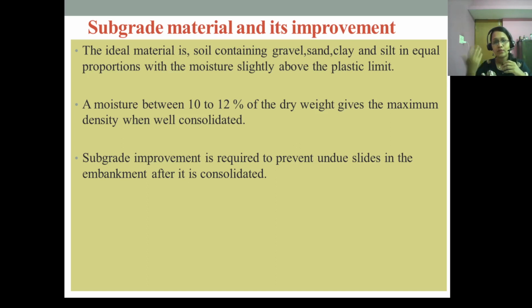Subgrade improvement is required to prevent undue subsidence and slides in the embankment after it is consolidated. Non-cohesive soils in the subgrade satisfy all the requirements of a good subgrade and do not need any improvement. But heavy clay pit soils, and loamy soils containing clay, should be avoided.